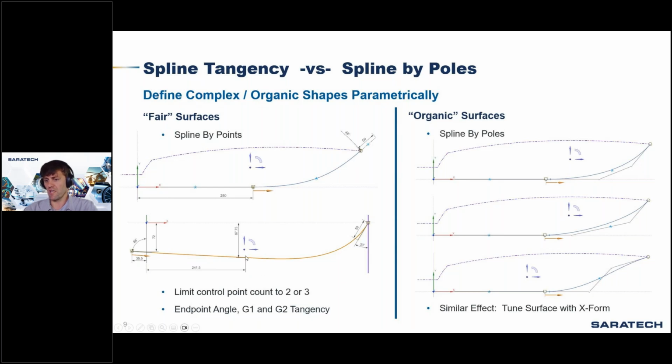If you did want to, perhaps like in this case, go from a convex curve in this profile view to a slight concave, I actually defined a midpoint and added a third point to that same spline by points definition.